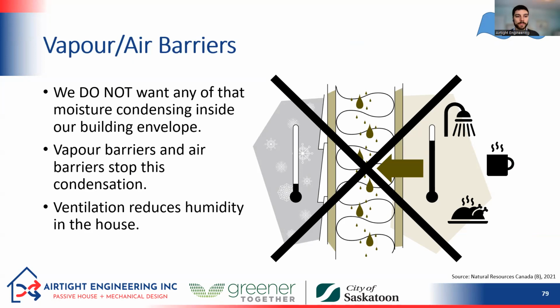So just a quick note on vapor barriers. We do not want any moisture condensing inside of our building envelope. And so we need to make sure that we're using both the vapor barriers and air barriers to stop this condensation. So we kind of use those both in tandem. We don't want any air leakage that's carrying moisture, and we also don't want any moisture just diffusing through the materials in our house.